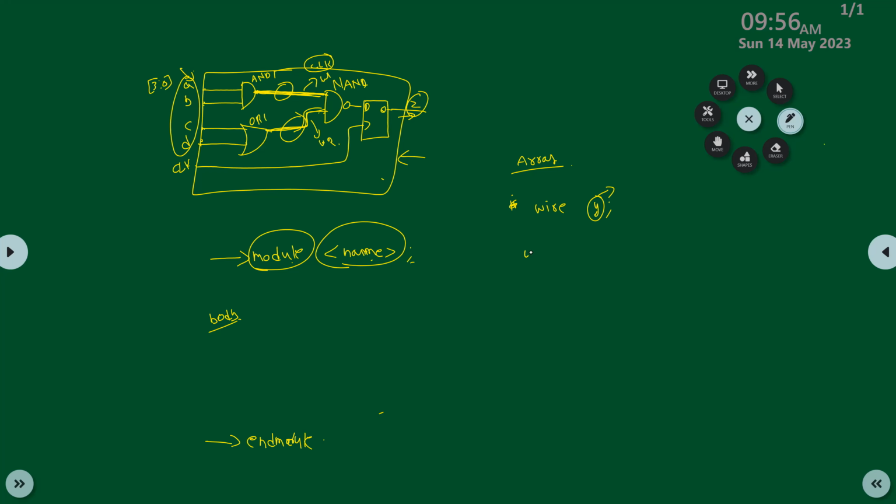If I define [3:0] y, y is a single variable and all 4 bits, 3, 2, 1, 0, are assigned memory, and you can access y. If you access y[1:0], that means bits 0 and 1 of y will be accessed. So this is one way of defining.